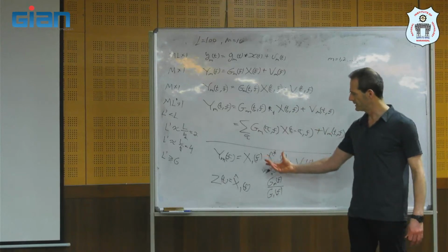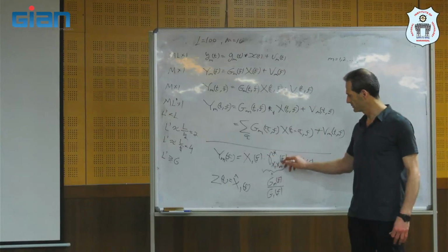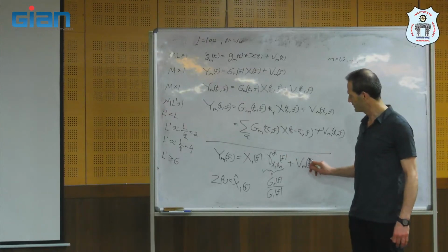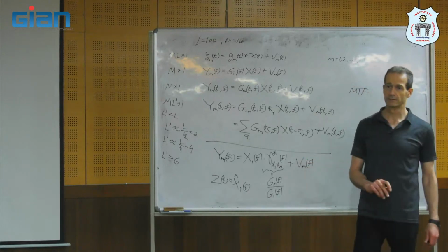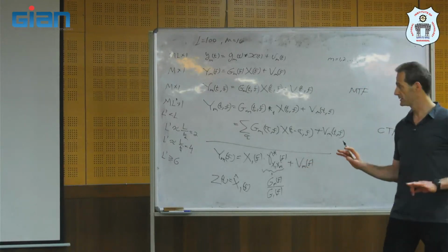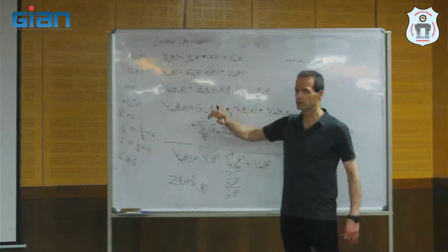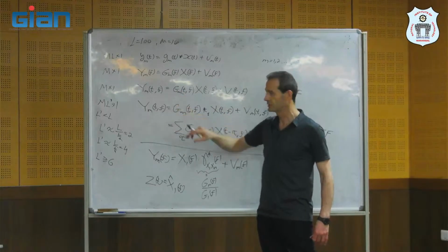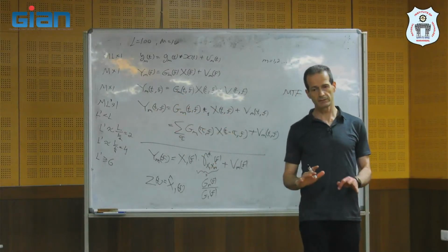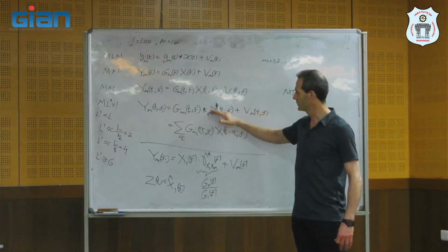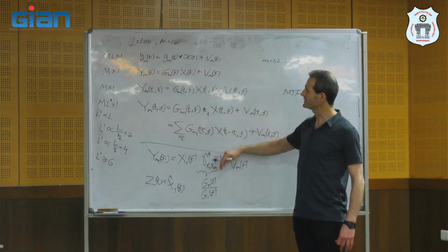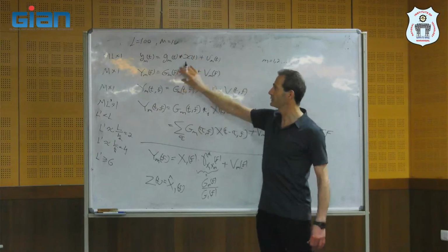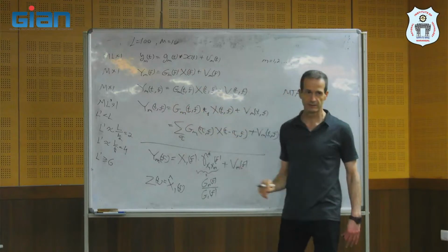So we need to know information about these relative transfer functions and the correlation matrix of the noise. For each frequency, we work with each frequency. And of course, you can do that with STFT, MTF, or CTF. But I'm not going to work further with this approximation because the extension is quite straightforward.